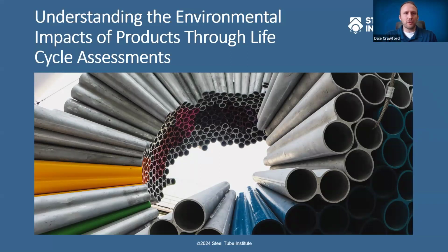Just remember that we're also interested in the electrical side of the world, the electrical conduit. What we experience quite often in our market, especially in the electrical world, is the architect and especially the design engineer will use conduit as the basis for design for many buildings and projects. And then oftentimes that is one of the first things that is value engineered out when it gets to the subcontractor level. That is concerning to us because there are many benefits to steel conduit over a different electrical raceway like MC cable or cable tray.